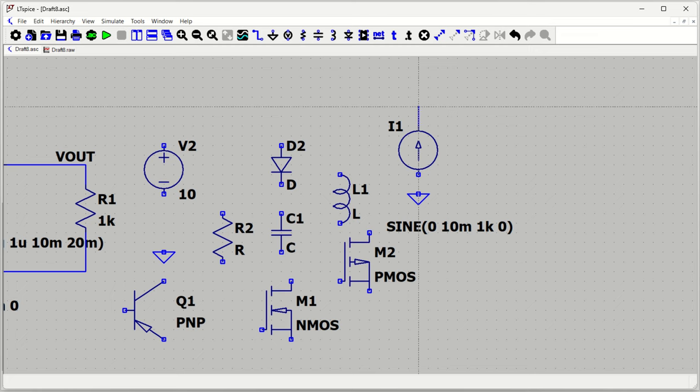Okay, net here, and then connect this also, W for net, W for this particular wire. Okay, W for wire, this net is actually nothing but wire. Net is for net naming. So if you want to have a net name, let's say I want to put I out, so this will be my I out on this particular net. Okay, now let us quickly run this.